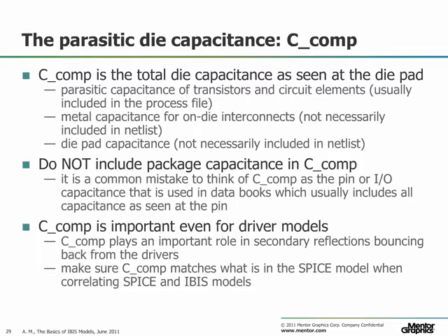You should also be aware that full transistor level models are not always accurately describing the die capacitance. This might happen because they don't always include all the metal interconnects that are found on the die or the metal capacitance formed by the die pad.